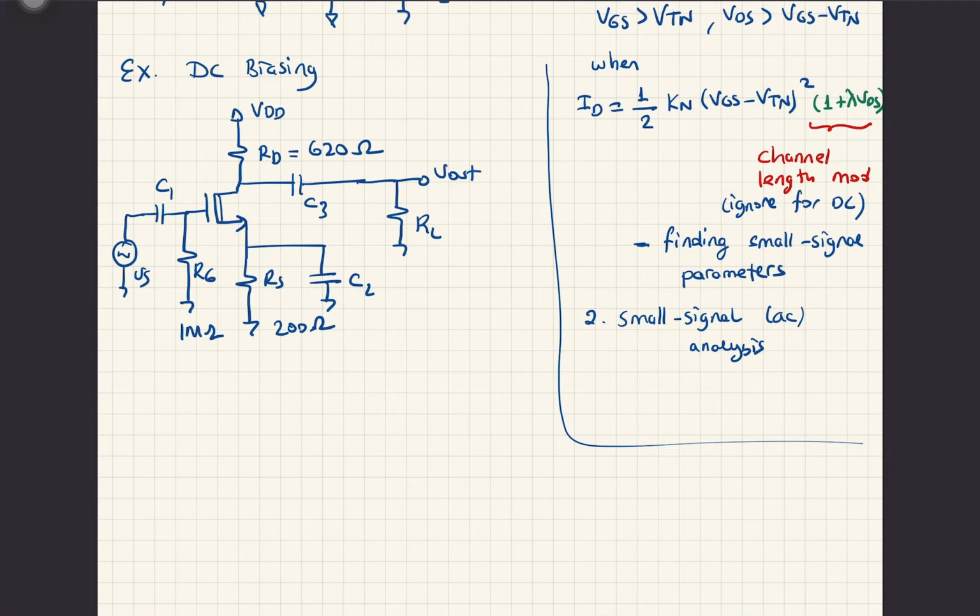and we have a different drawing in here which indicates that MOSFET is depletion type NMOS. So what will be the difference by using a depletion type NMOS? Basically nothing. All the DC analysis will be the same, but the only difference is the threshold voltage is negative. That's the only difference. Other than that, we are going to use the same mathematical formulas and everything.